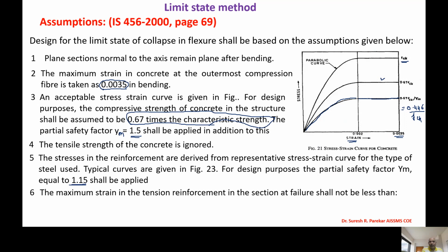Then the maximum strain in tension reinforcement at failure is not less than the value given here, which is fy upon 1.15 Es.